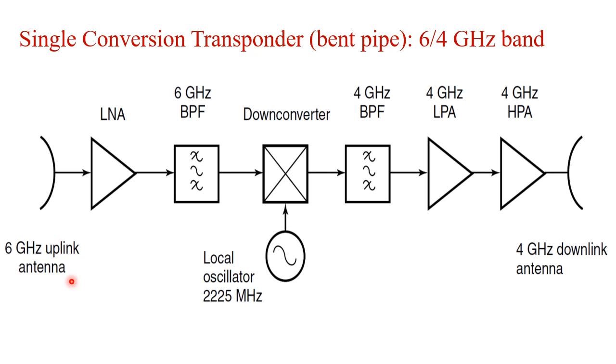To make the antenna beam narrow enough, it requires huge gain actually. The antenna gain of the ground station transmitter antenna must be very high, right? Now, if we use a higher range of frequency, then the same antenna will provide larger gain.